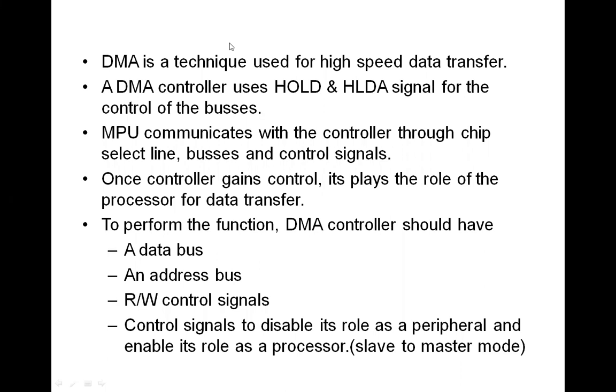And whenever the work is over, meaning the data transfer is over, the controller will send a low signal onto the hold line so that the microprocessor will know that the operation is over. Now it resumes its work.